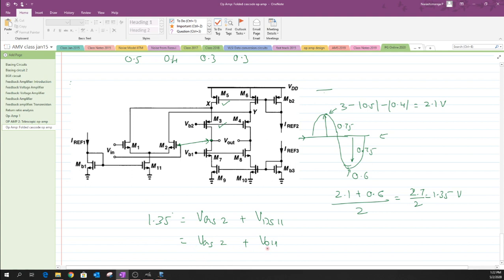and let us have maybe around 0.5 volt for this, just because we have dedicated 0.5 volt for a PMOS device that carries 1.5 milliamperes. Even in this case, this M11 transistor, even though it's an NMOS device, also carries a current value of 1.5 milliamperes.